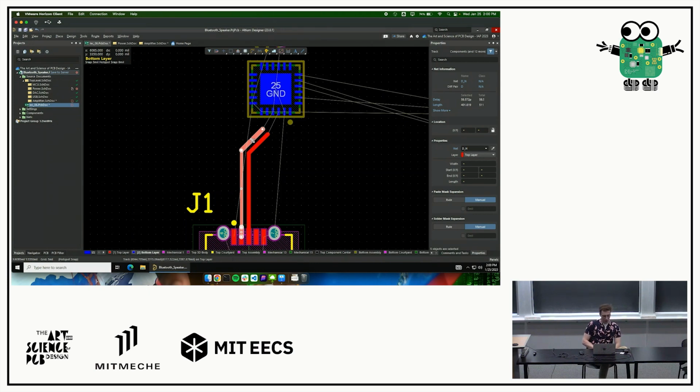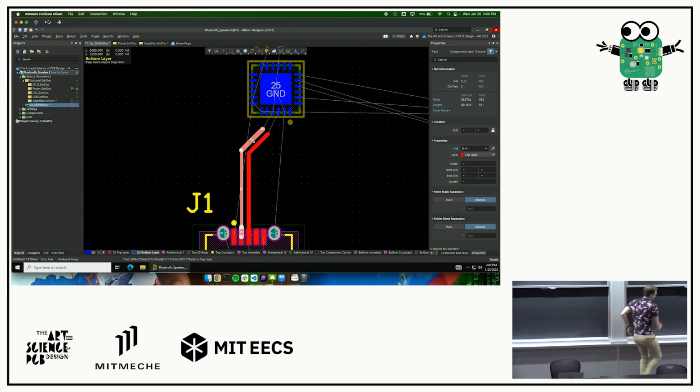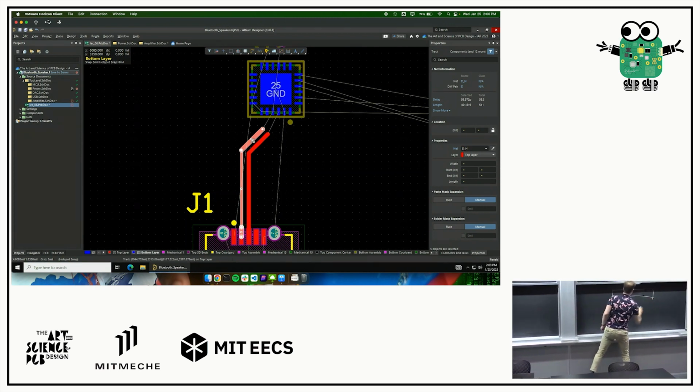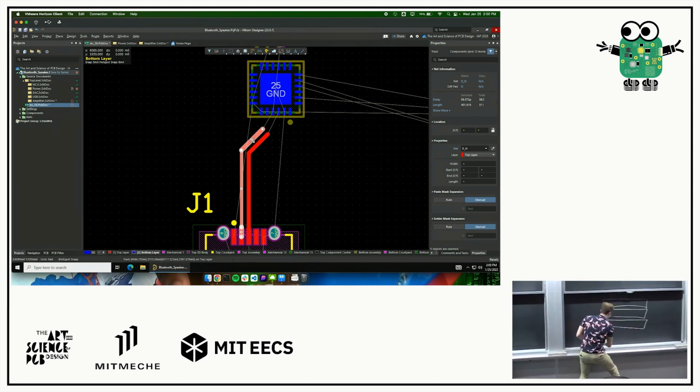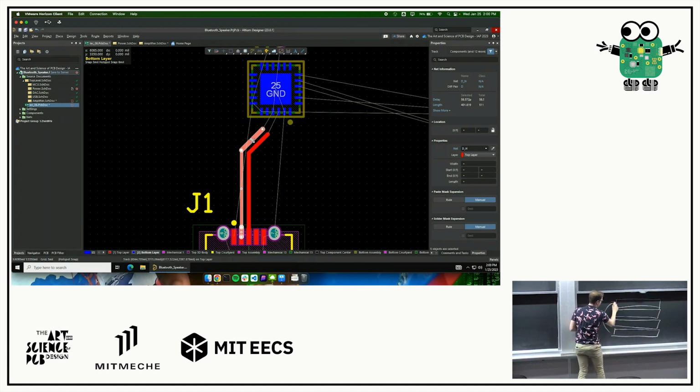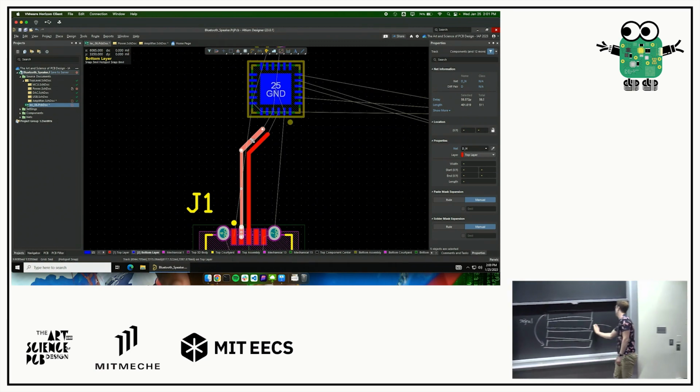So there's a little bit of a distinction to make here. Normally, when we're doing 2-layer boards, power and ground planes are something that we care a lot about on multi-layer boards. If we've got a 4-layer board, a lot of times the methodology is you'll have top copper, then an internal layer, and then a bottom layer. Normally people will make the top and bottom layers signal, and parts will mount to the tops and bottoms of the boards. And then on the inside, they'll pick one layer to be power and one to be ground.